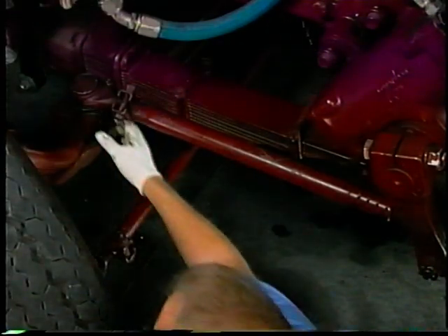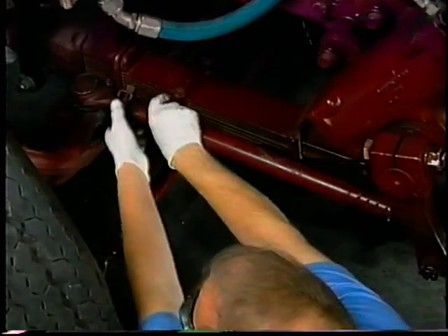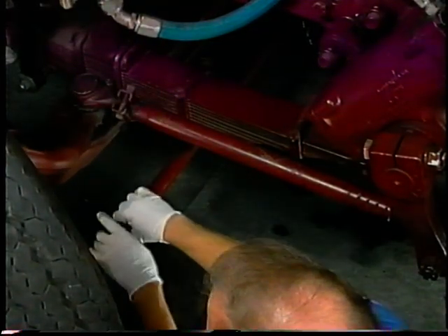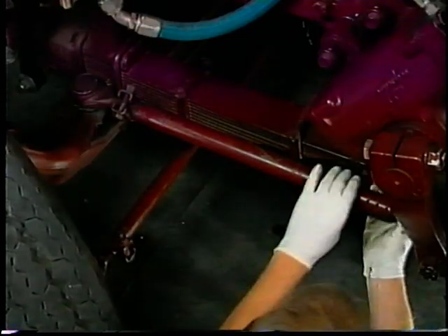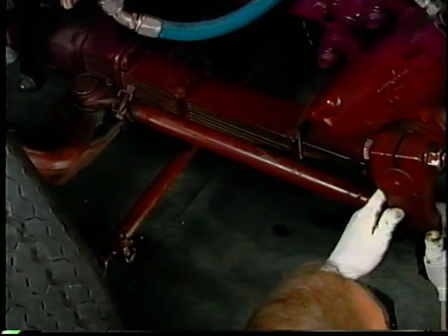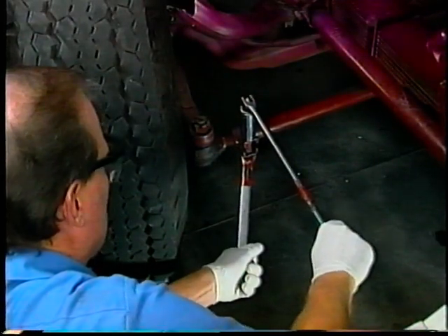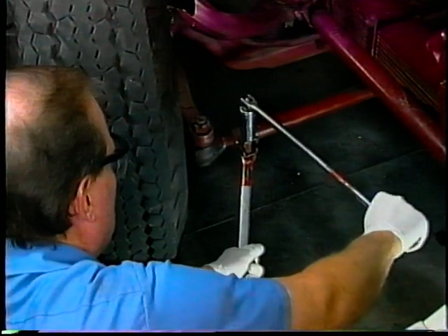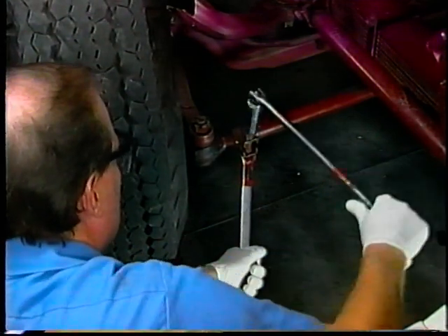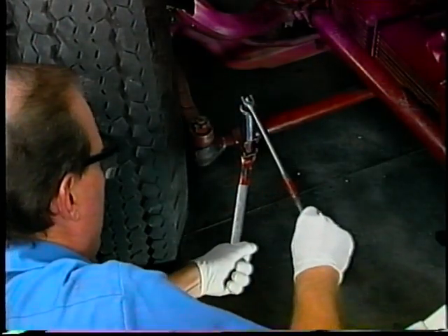You can test each of these parts by looking for signs of wear or damage and by pushing against them with your hand to check for excessive movement. Never pry on the linkage or use excessive force when testing them, as good components can be damaged. Any worn linkage, bushing, or bearing will require replacement and a check of the alignment after replacement. Make sure all lock mechanisms are properly reinstalled.